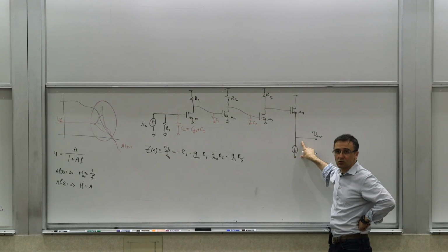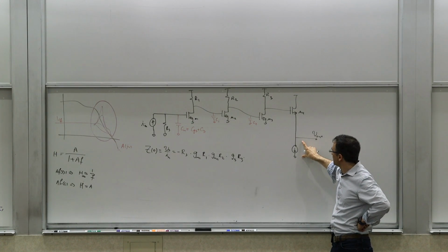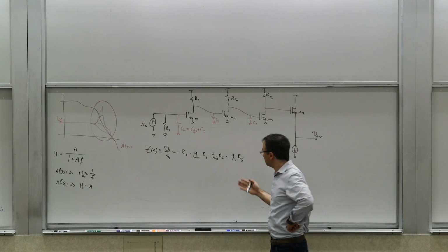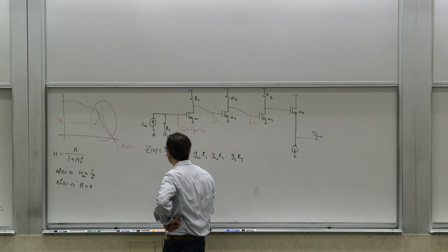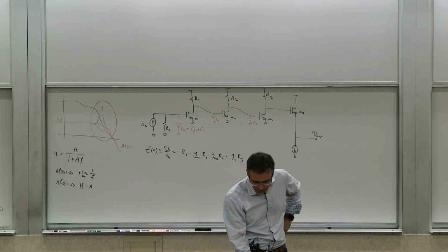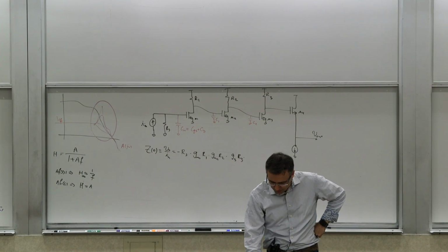1, right, because it's an ideal current source. So it's a voltage divider, a resistive divider between infinity and Rm. So it's 1. This is your low frequency transfer function. That's Z naught, and you can evaluate it, estimate it, or calculate it.